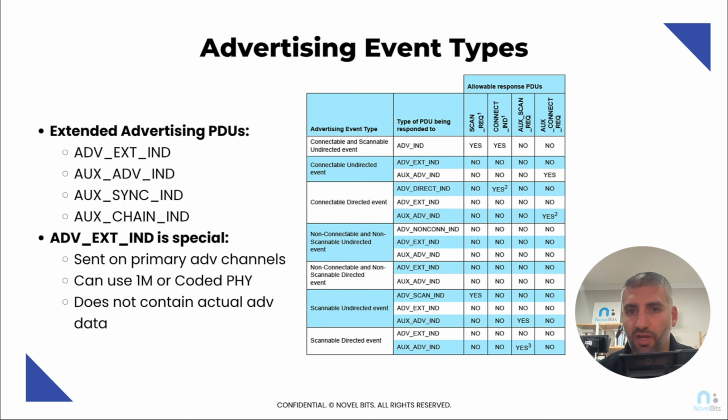It is optional, but it is available to achieve long-range communication. We've seen videos of this achieving miles of communication and exchange of data between Bluetooth Low Energy devices, especially line of sight. And this coded PHY allows you to do that by adding some redundancy in the data rather than requiring you to increase the transmit power. So again, this PDU type does not actually contain any advertising data.